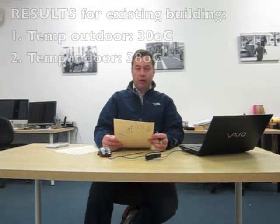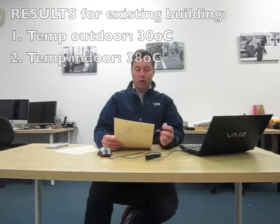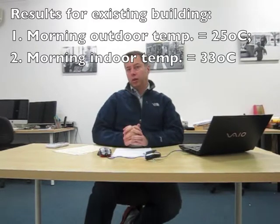Following the construction of the building model, the results were quite interesting, and they showed that for a 30-degree summer day, the indoor temperature would rise to 38 degrees. This happened around 4 p.m. In addition, in the morning at 8 a.m., when outside the temperature was 25 degrees, inside when the workers would start work, the model showed that the temperature was 33 degrees Celsius.